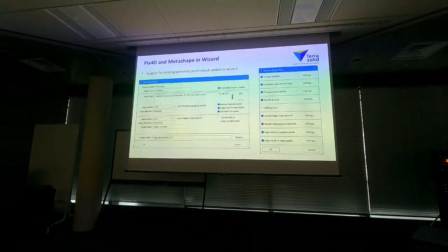But the rest of the steps I have, and if I have Metashape, then I have low reliability, which uses what Metashape calls confidence values. If confidence is written into the LAS files, TerraScan can make use of that to exclude the less reliable points where we have better reliability close by.